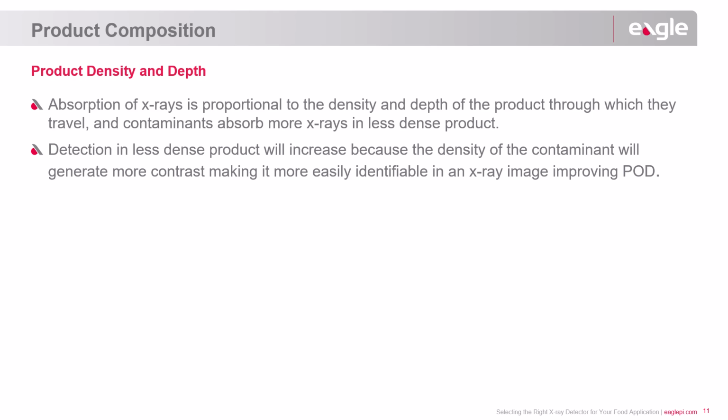Typically, the main factor influencing the lifespan of your X-ray tube is the milliampere setting. Generally, the lower the mA, the longer the X-ray tube will last. However, if your product is particularly thick or has a high salt content, such as cheese, you may need to increase the X-ray energy to achieve effective penetration.